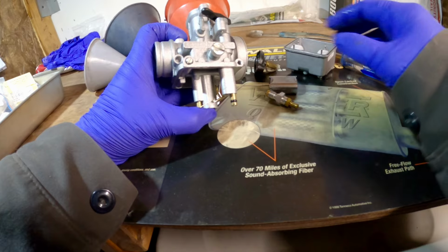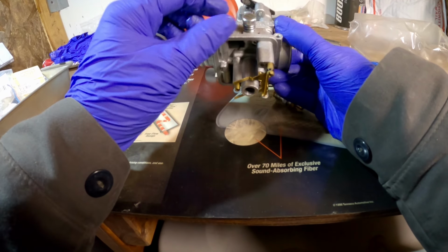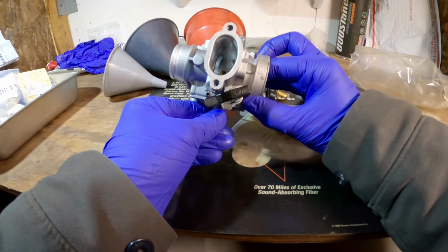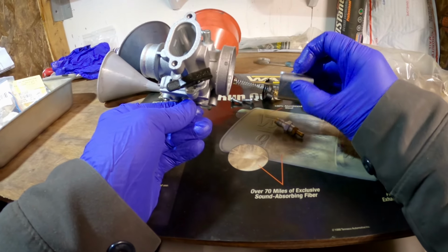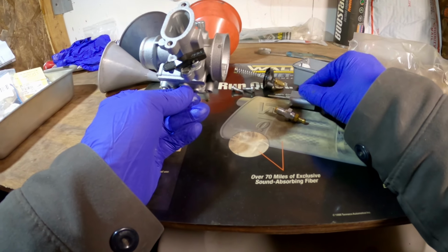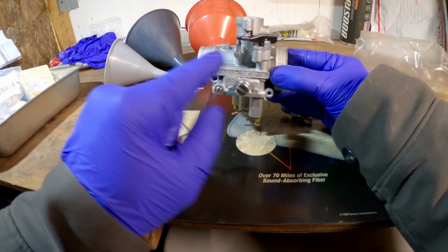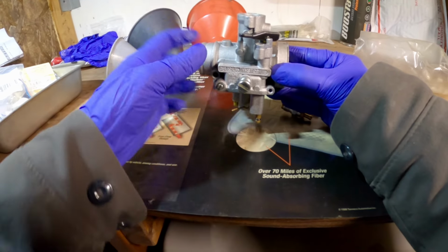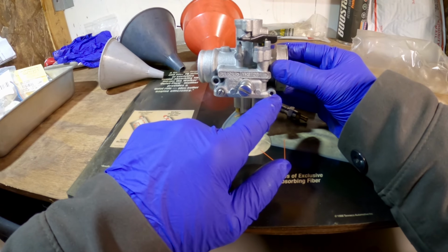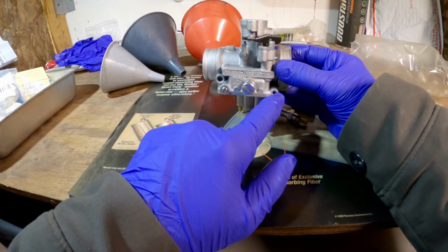And here's our air screw, or the fuel screw in this case. This would be our idle adjust knob. You can see down in there, that's going to interface with that edge and set your idle. Because this adjustment screw is after the slide, so airflow is this way, this is going to be your fuel screw. And like on the PWK, there's a screw on this side before the slide, and that's going to be your air screw.